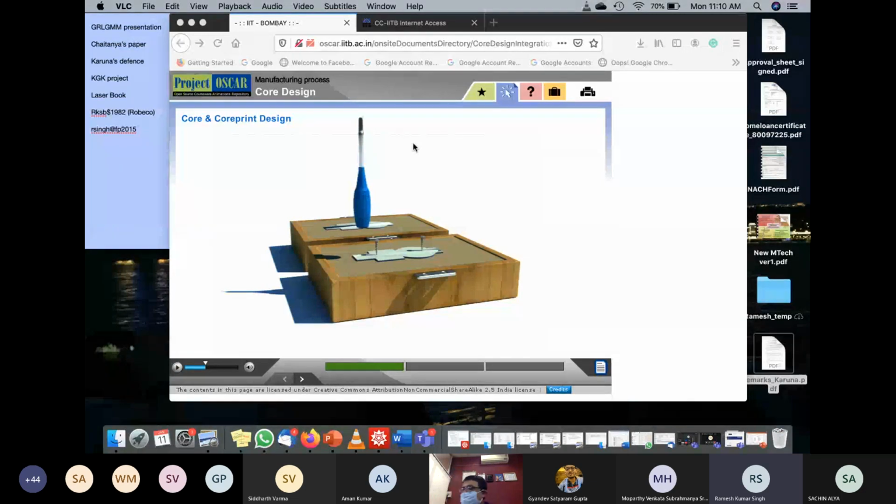In die cast, what happens is you have a permanent mold, right? And then what you do is you have to fill the permanent mold cavity. Yes or no? How do you fill the permanent mold cavity? What are the ways of filling it, in your opinion? I can pour it. So the gravity head will let the mold be full, right? That's one way to do it.